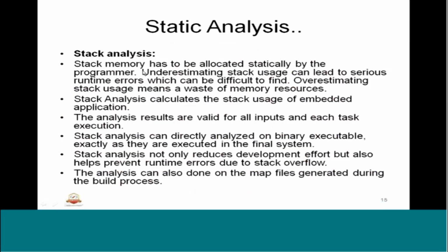That means the implementation code should have a stack memory, definitely, because we use interrupts or preemption of the various small functions by bigger functions, or preemption of bigger procedures by smaller functions. Definitely the program state and the variable states all have to be saved and should be recalled. So that is the use of a stack.